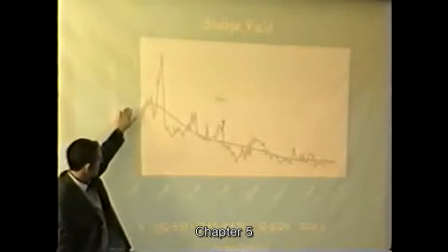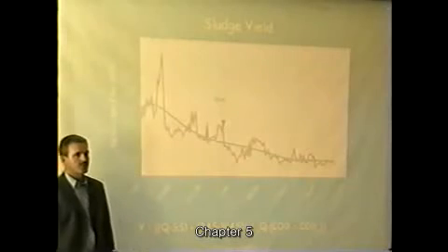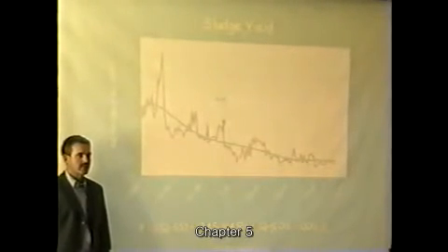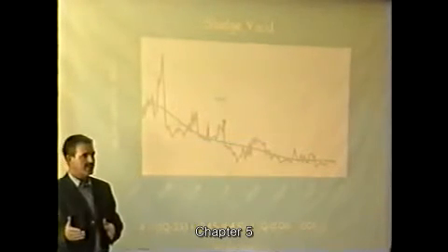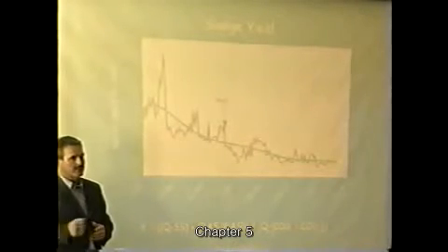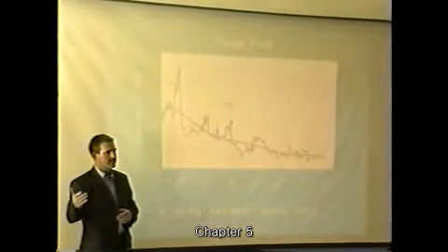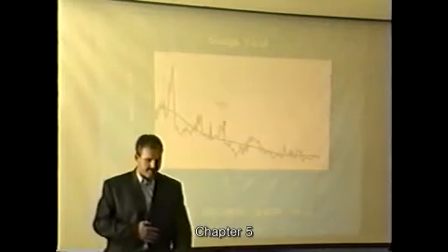It dropped from about 0.2 to 0.05, which was close to a 70% reduction in sludge production. The simple reason for that is if a system is under stress, you're producing the acids. The acids are food for archaea under low dissolved oxygen concentrations, and they are removed, in other words, as methane, and you don't produce excess biomass.